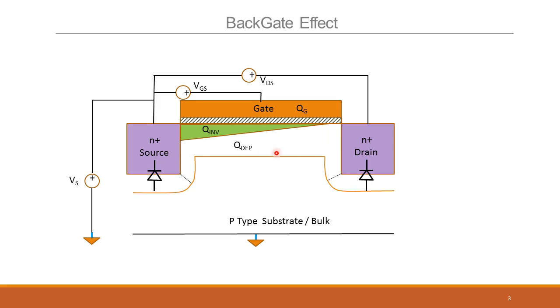Right? So Q depletion, arbitrarily, we'll take at some point where, let's say, it is in this region. Qualitatively, let's say it is only in this region. Right? These depletion region charges are purely because of the drain and the source and are not impacted by the VGS. They are too far from the VGS to get impacted by the channel potential. Right?